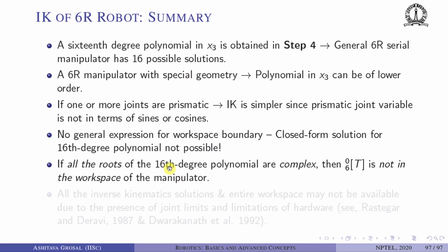So how do I find the workspace? If all the roots of the 16-degree polynomial are complex, then this position and orientation is not in the workspace of the manipulator. This is an important concept. So I have given you a 16-degree polynomial. I go to MATLAB and find the solution of this 16-degree polynomial and see that all the roots are complex conjugates. Then the point from which I got the 16-degree polynomial is outside the workspace.